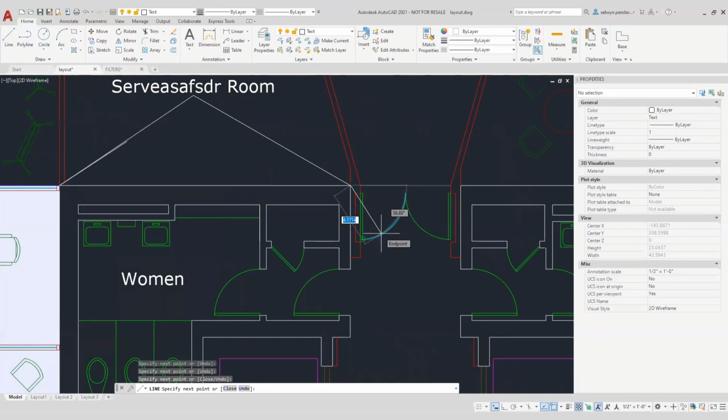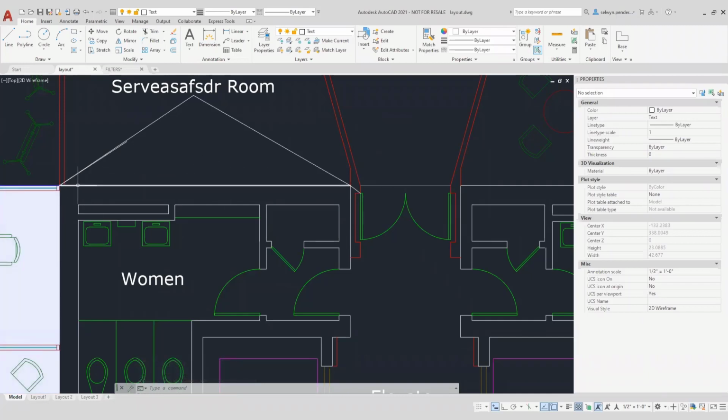So I might want to snap to the center of that arc. Once that grip over there displays, I can click onto that center. So that's an easy one with the grips. If you're in a congested area and you can't get to the endpoint or midpoint or whatever it may be, you can click somewhere on the line and have your O-snap set and just press the tab button, and it will cycle through all the O-snap items or areas that are available for that object.